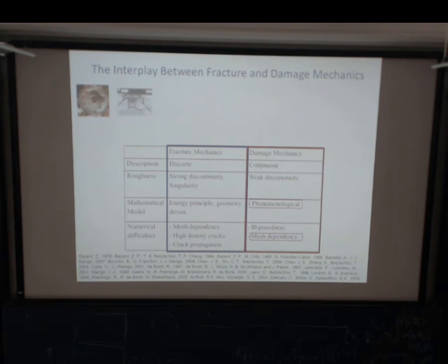If I don't have to deal with the whole structure, if I just take a sample, say a representative volume, then it is possible that I can still afford to use fractional mechanics. And I'll see how I can link from fractional mechanics, from a sample, and extract some damage law and use the damage law for upper scale calculation. So that's what we are trying to do.